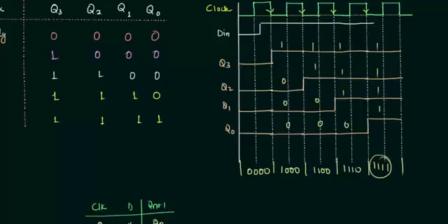This was our number that we wanted to store, and it is stored in the shift register, and it is shifting. Let me show you why we call it shift register, because the data is shifting. This 0 was shifted here, this 0 shifted here, then again here. This one you can see is shifted like this. So the data is shifting, that's why we call it shift register, and it is a very simple concept. We have used D flip-flops and their properties to make this multi-bit storage element.